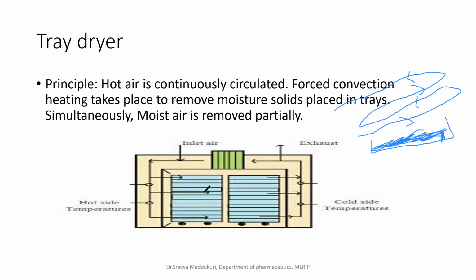During the heating process, the material is spread out on the trays. Heated air is directed to flow in a circulation form. It flows over the material in the trays, and trays can have a solid, perforated or wire mesh base, right? The fresh air is combined with heated air in a fixed proportion for efficient performance. The tray dryers take air from outside, and the fresh air is combined with hot air for efficient performance.